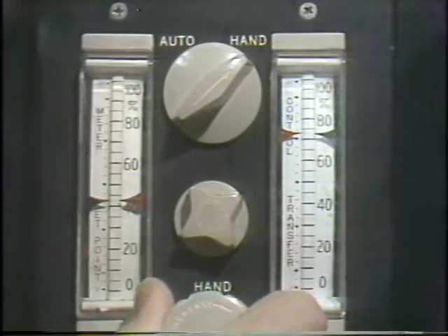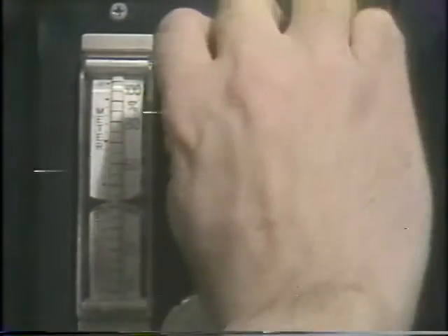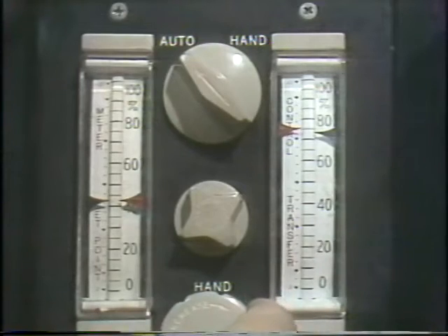After the instrument is restored to service, check to make sure that the instrument is working properly in manual. There shouldn't be any leaks or other obvious problems. Then have the operator place the system in automatic and check to make sure it works properly. Once you've restored the instrument to service, you also need to make sure there aren't any other problems in the system. Sometimes a problem can be due to one or more causes. You may fix one of them, but you have to make sure there aren't any others. And if there are, you'll have to troubleshoot each problem one at a time using the troubleshooting procedure.